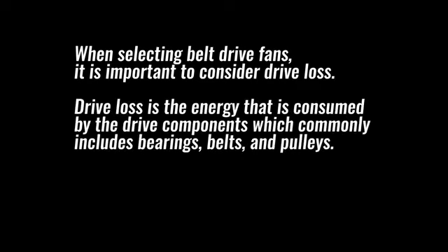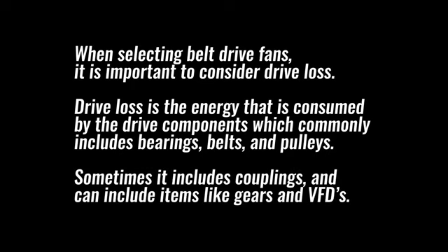Drive loss, what it is and how to account for it. When selecting belt drive fans, it is important to consider drive loss. Drive loss is the energy that is consumed by the drive components, which commonly includes bearings, belts, and pulleys. Sometimes it includes couplings and can include items like gears and VFDs.